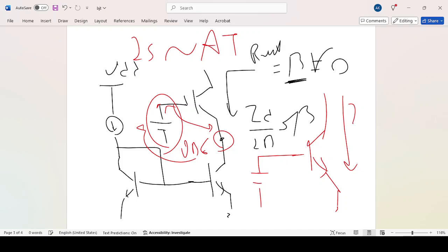IC will flow through the BJT and generate some heat, and then this changes IS, and when IS is increasing, IC increases too, and you generate a loop that increases IC in a way that you cannot stop, and limits the functionality of the BJTs.